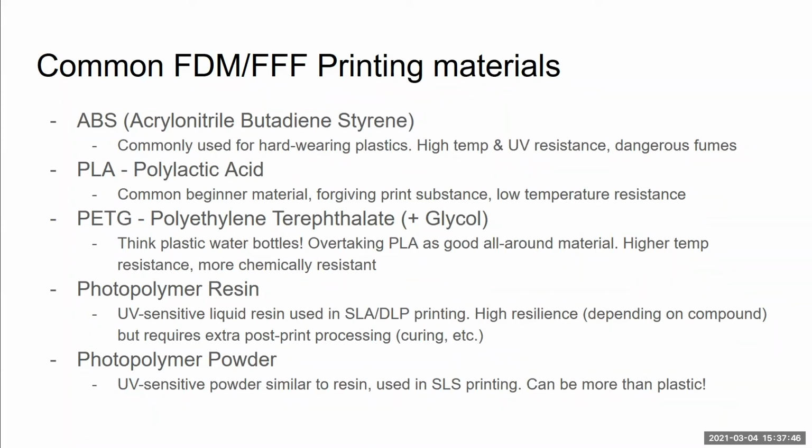And they're also normally a lot stronger, so the bonds between layers are a lot stronger. There have been some PLA prints that I've done that you can just sort of break apart layer by hand. The resin prints that I've done, there's no way that I could do that without like a jackhammer or a sledgehammer or something crazy. So they're a lot stronger, but they are a little bit more expensive and they're a little bit more dangerous because there are some potential health risks if handled improperly. So something to keep in mind.